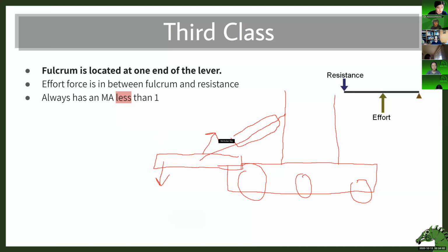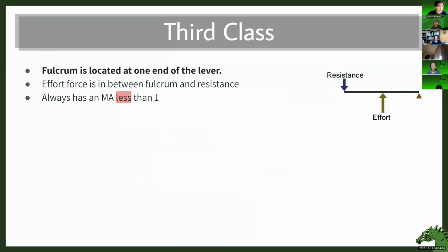All right, the resistance force and your applied force upward from your piston. Right here, resistance, effort, third class lever. So again, we also are careful in placing the location of this pivot, because if it's too close, this piston won't be able to lift it. And if it's too far, it's probably not going to be able to package properly. But I guess that's for later.